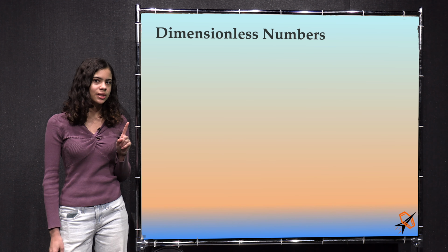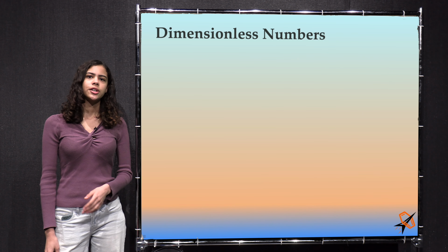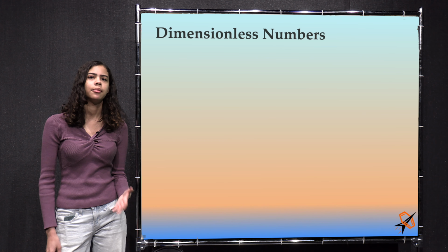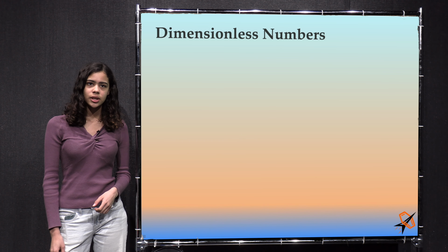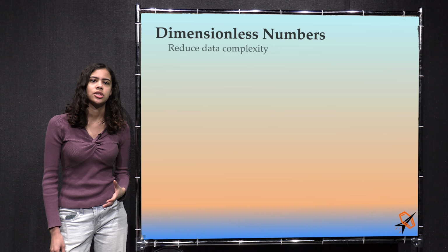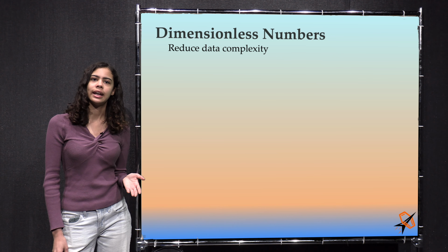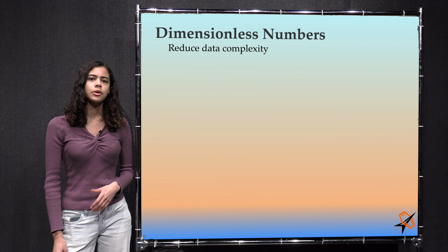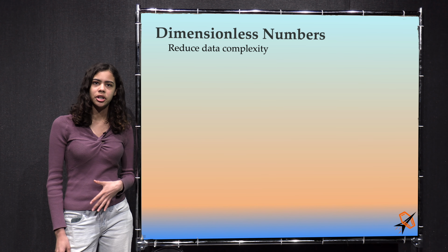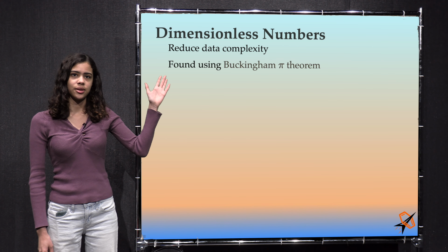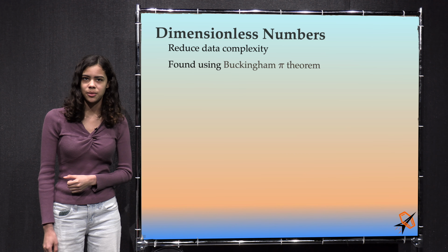Concept 1. Dimensionless numbers. Engineers often have to do a lot of experiments and try to determine relationships in an empirical fashion. Over the years, they have tried a number of ways to reduce the number of measurements they have to make and get the maximum information they can out of their measurements. The most popular way to cut down on the number of variables that need to be correlated is to use the Buckingham Pi theorem to create dimensionless numbers or groups.